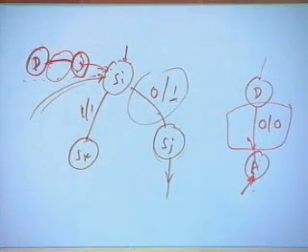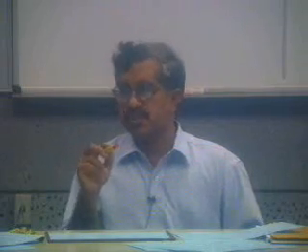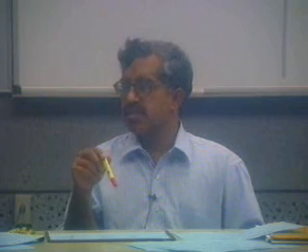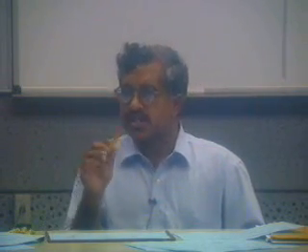Again, one assumption is that the nature of your state machine graph is such that all the states are reachable from all the other states. You reach any state, there is a path available, there is a set of transitions available to reach any other state. So, under these two assumptions, it is possible to exactly verify your state machine transition by transition if you can derive first the homing sequence and the distinguishing sequence. Of course, we know that a distinguishing sequence will exist if there are no redundant states. And we also know that a distinguishing sequence is a homing sequence. So, basically for any state machine which has no redundant states, you can actually derive both a homing sequence and a distinguishing sequence, and once you can do that, then you can verify that the state machine is correct.